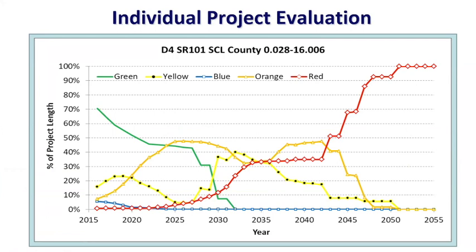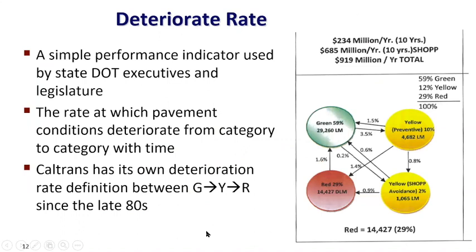You can decide what kind of treatment you do, and you can also use this post-mile range to do lane-by-lane analysis to see which lane you want to fix first, right? So this is very, very informative for us when we use PaveM. That's something we really like.